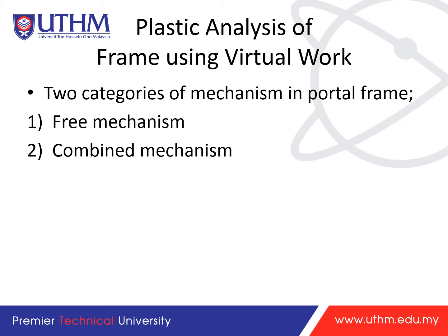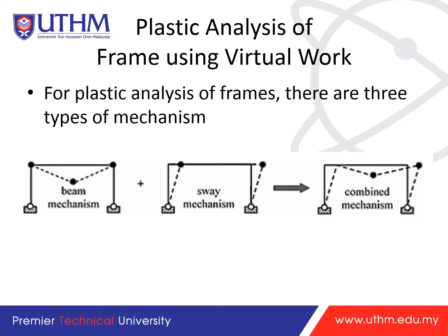For this video I will explain the plastic analysis of frames using the virtual work method. There are two categories of mechanism in a portal frame: number one, the free mechanism, and number two, the combined mechanism. For plastic analysis of a frame, there are three types of mechanism.